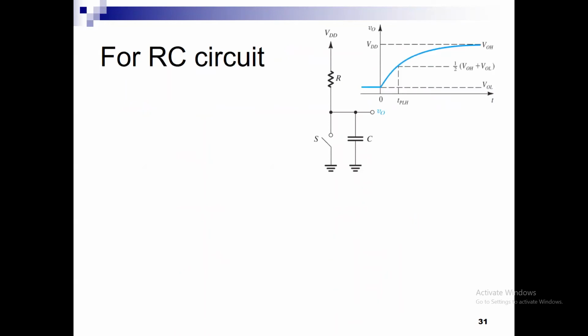So we're going to start with the resistor pulling up the capacitor just because the I average is simple to demonstrate, and then we will move on to the case of the transistors. So for the same example, where the resistor is charging the capacitor, we're assuming that VO is at VOL at T0, and at TP low to high that VO is half VOL plus VOH. Okay, so the capacitor voltage is moving from this point to this point.